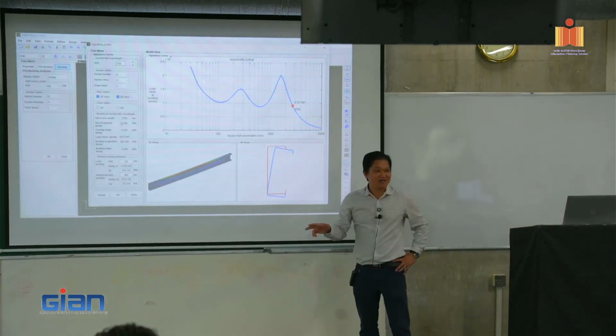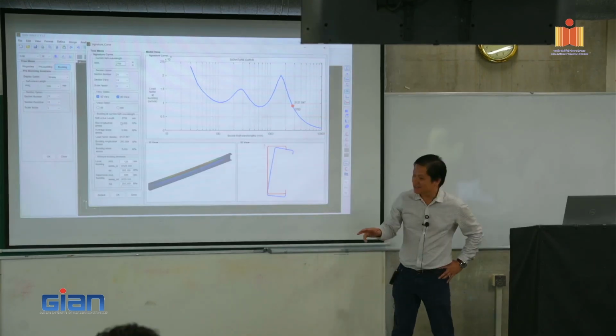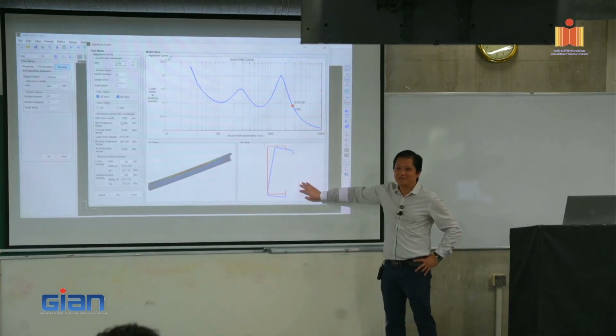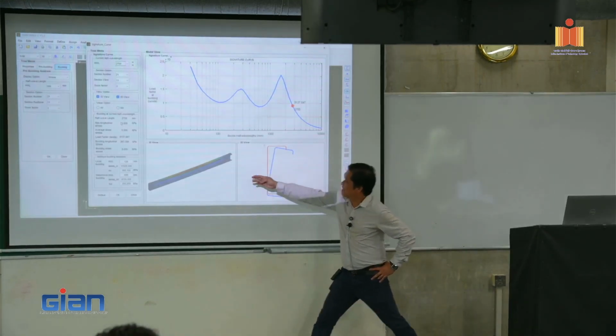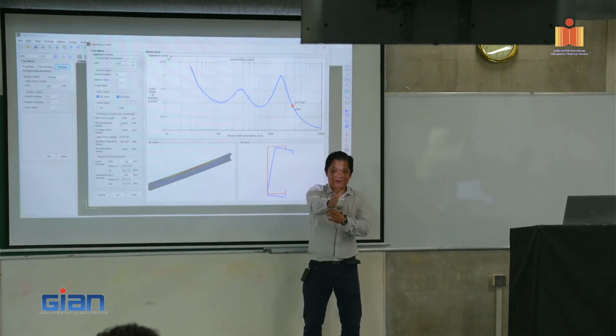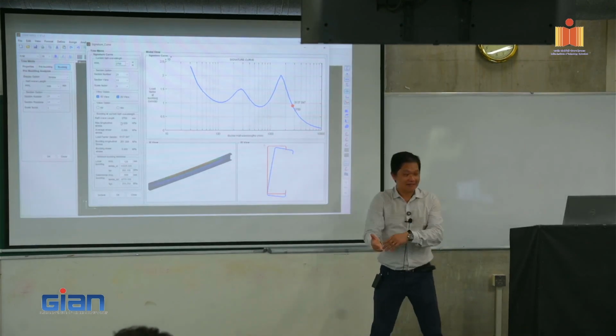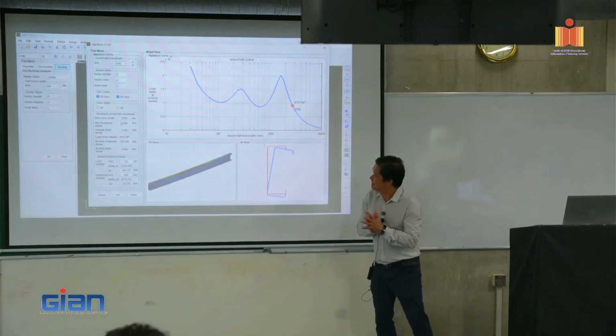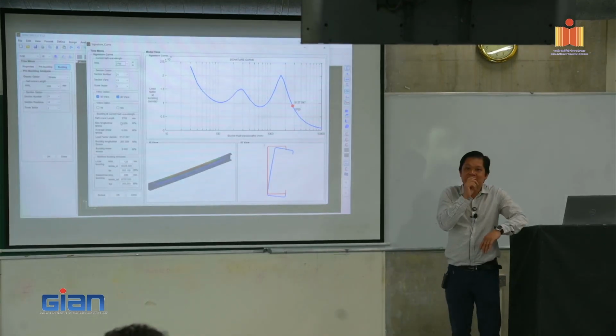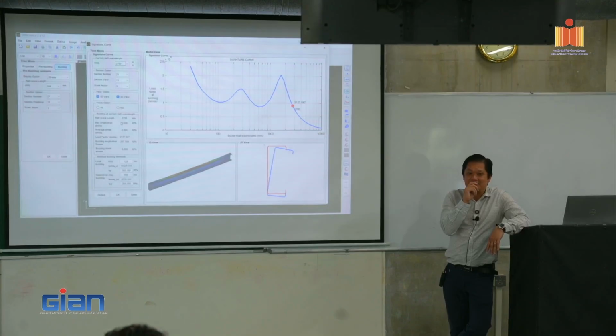So now, what's interesting here? What do you see, when it's buckled? Yes. So right in the middle, it buckles sideways and twists. Right? Get it? And what else do you think is interesting here when it's flexural torsional buckling?